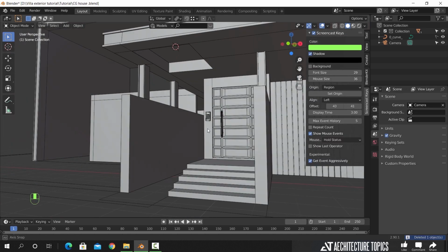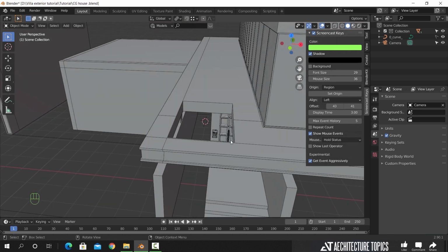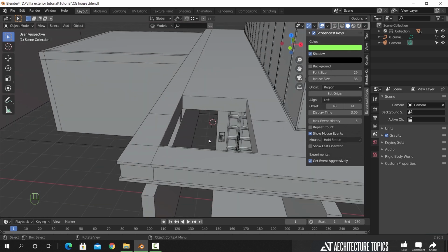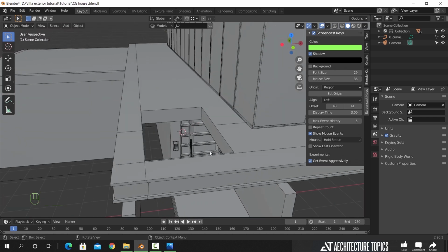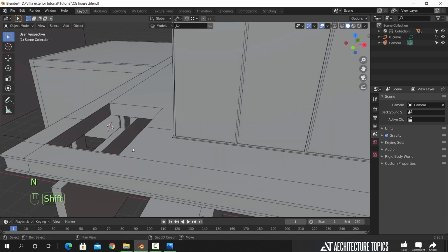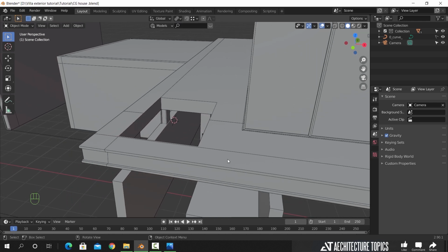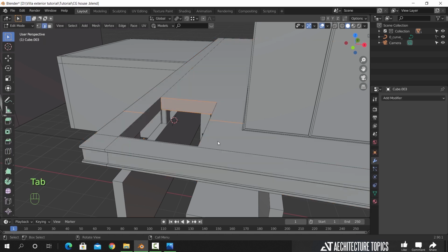In this new opening we made, we need to mark the black metal areas, and add some depth to the vertical faces. Now after the boolean, Ctrl R won't work.